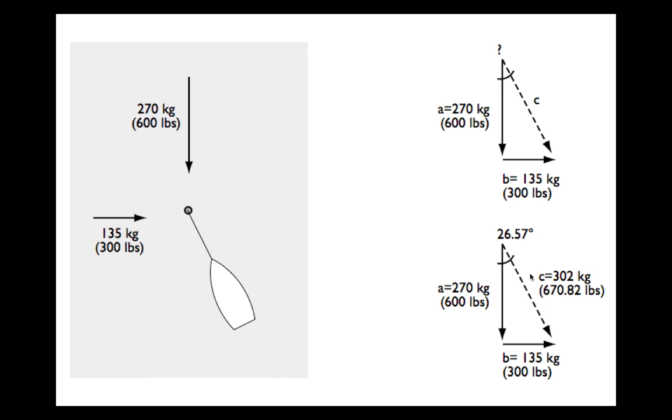And notice too that they both influence the direction of the resultant, right? The angle of the resultant. And in this case, because we have a greater vertical force, it's going to be a slightly steeper angle than we might expect. What we've done here is we've taken these two forces and we have figured out what they add up to. We can now come in and we could actually design that mooring line. We know what it has to be capable of resisting.